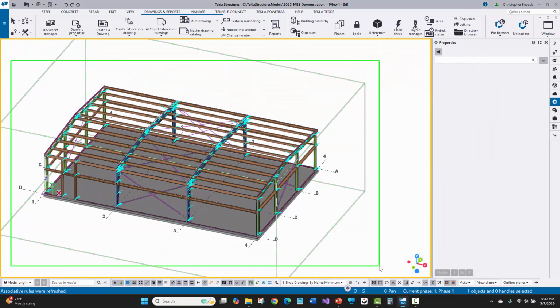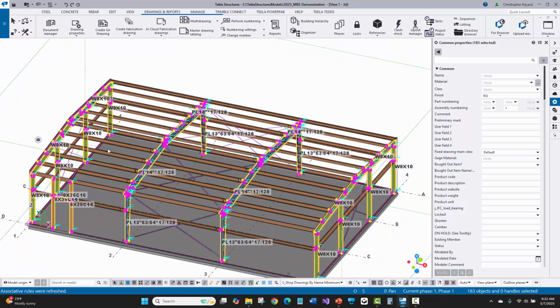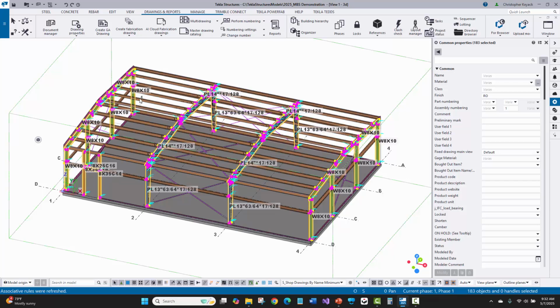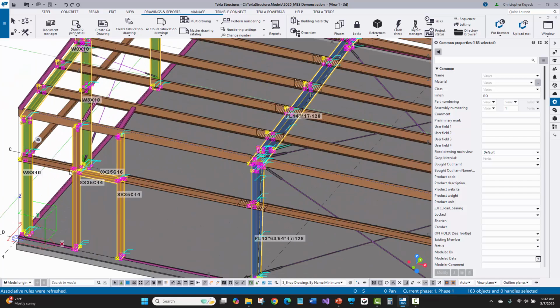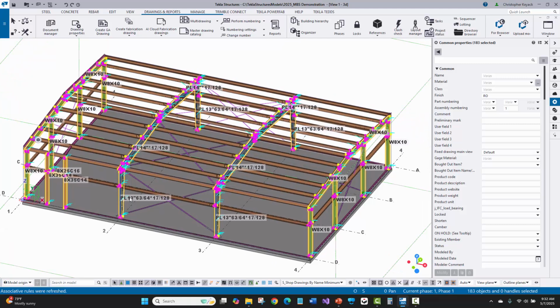And if I window around the model, you'll see that it highlights only the steel of the things that I want to make assembly drawings from. And so that makes sense. I don't want any girt and purlin drawings because there's nothing special about those. We'll just cover that in our cold form report and on the shipper. But everything else here, because I've got welded clips on the jambs and the header, and I've got my hot rolled end walls, and then I've got my 3-plate rigid frames here, I want to go ahead and create drawings from this.